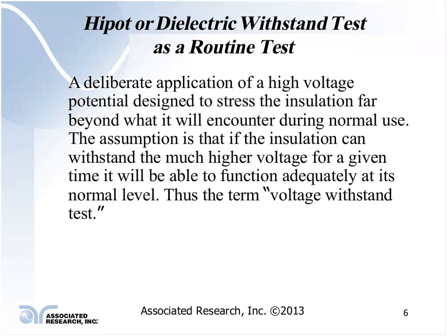Okay. Let's talk about the routine Hipot test. What is done at the end of your production line? What is it designed to do? Again, this test is a deliberate application of a high voltage potential that is designed to stress the insulation far beyond what it will normally encounter during its normal life cycle.